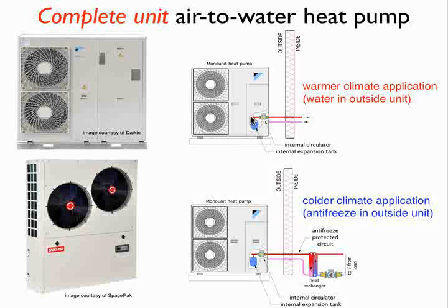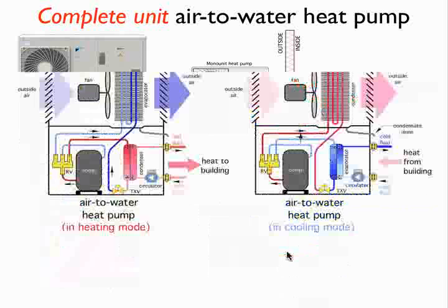So this lower schematic shows a system where we're tying the outdoor unit to a brazed plate heat exchanger, and we are using an antifreeze fluid between that outdoor unit and that heat exchanger. Some manufacturers mandate this for these units, again, in a cold climate where you have frequent freezing, sub-freezing conditions. This is the preferred installation technique.